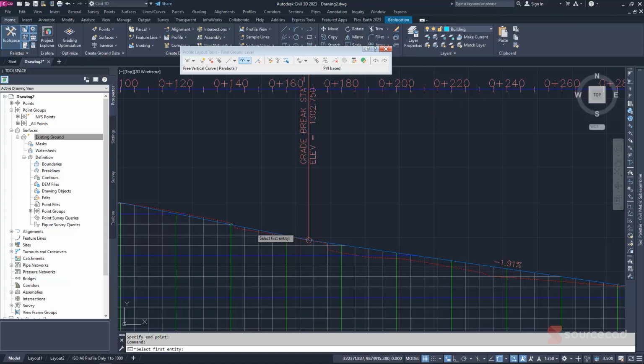The next entity being this one. And you can specify either the curve length or the K parameter or the pass-through. You can see this over here. By default, our section length, or our curve length, has to be greater than or equal to the design speed in accordance to the standard that you're using, or has to be 2 VD, twice the design speed.